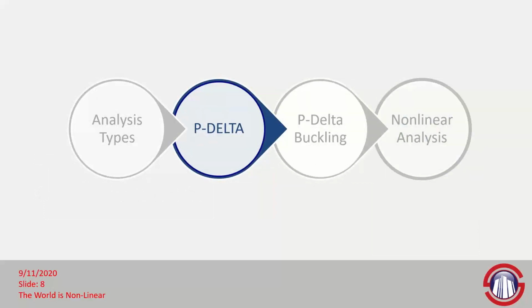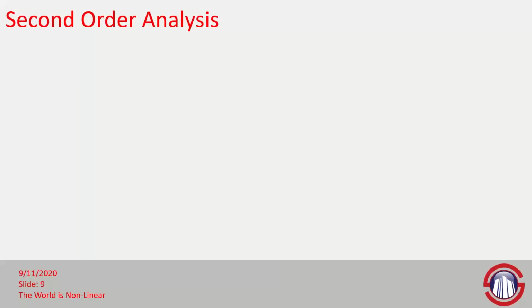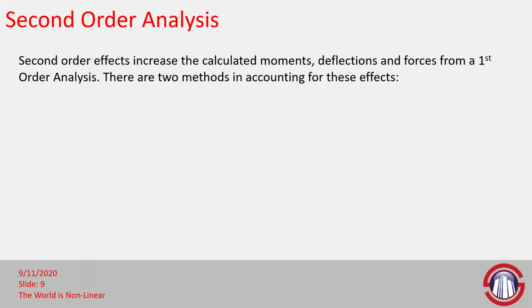Let's start by looking at P-Delta analysis. And this occurs when second order effects will increase the calculated moments or deflections and forces that you would normally experience during a first order analysis.